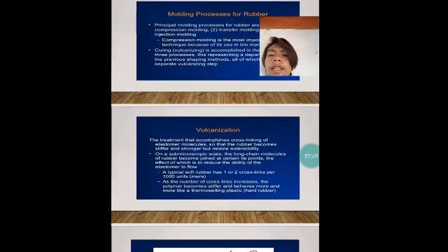The treatment that accomplishes cross-linking of elastomer molecules so that the rubber becomes stiffer and stronger but retains its extensibility. On a submicroscopic scale, the long chain molecules of rubber become joined at certain tie points, the effect of which is to reduce the ability of the elastomer to flow. A typical soft rubber has one or two crosslinks per 1,000 units. As the number of crosslinks increases, the polymer becomes stiffer and behaves more and more like a thermoplastic, as in hard rubber.